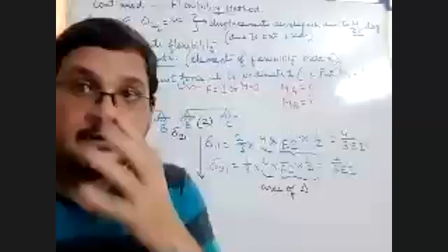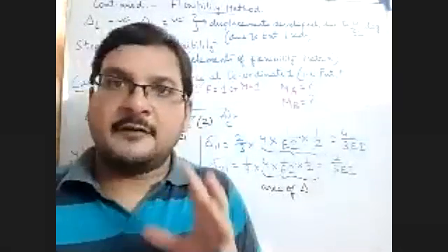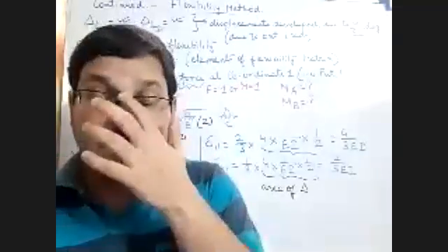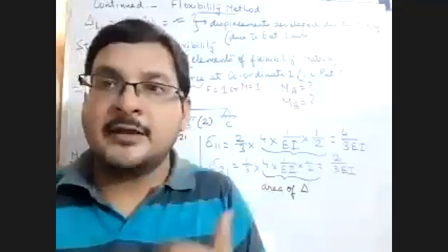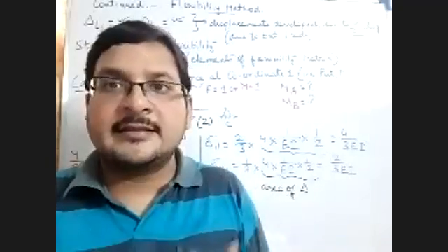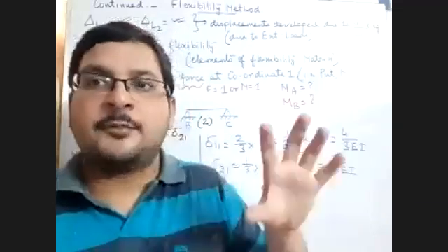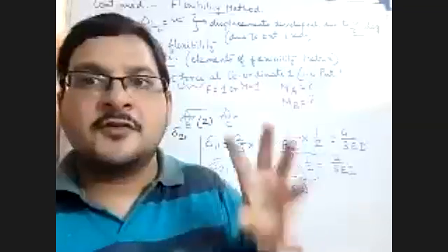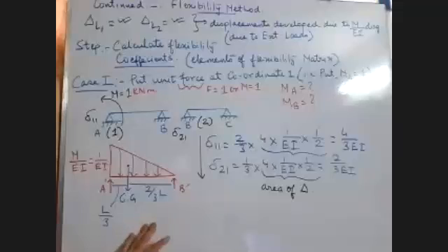So please remember, whenever we find out the elements of a matrix, whether it is a flexibility matrix or a stiffness matrix, we will calculate case wise. For example, if we have n coordinates, then there will be n number of cases. The more the number of coordinates, the more the cases. So case wise, at the respective case, we will put the unit force. Please take this down. If you have taken down, you can write in the chat box. Then I can go to the next case.